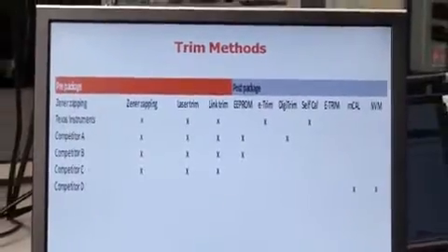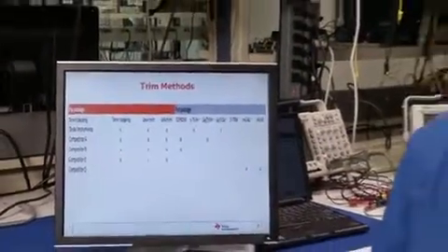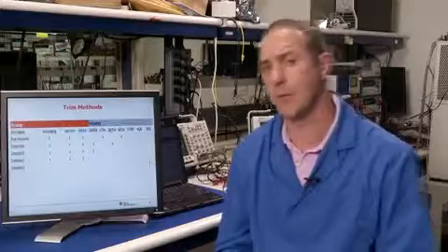Speaking of applications, there are, of course, many of them where E-trim would make sense, and there are many of them also where a zero drift technology would make sense over an E-trimmed or a trimmed device. Here's an example. If we're talking about an industrial application like downhole drilling, for example, where temperatures are so extreme they can reach up perhaps to 200 degrees Celsius or even north of that. The problem is that when you use an E-trim device, you're not likely to get the same temperature drift or the temp code that you would normally get with a zero drift device, and hence the name zero drift, by the way. These are usually well below a microvolt, okay? Well below a microvolt, meaning sometimes even below 100 nanovolts.